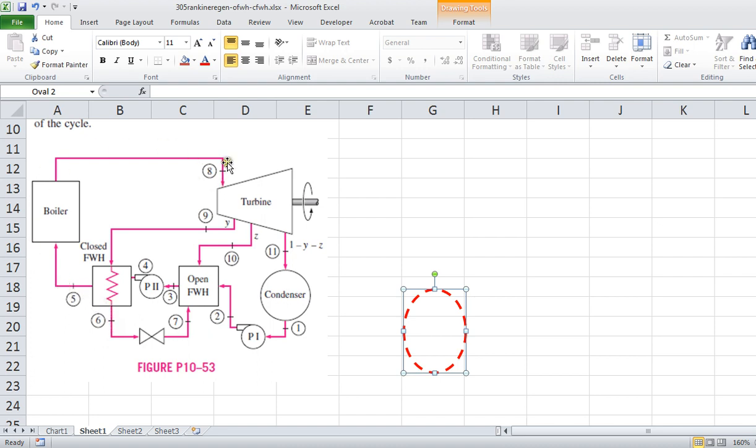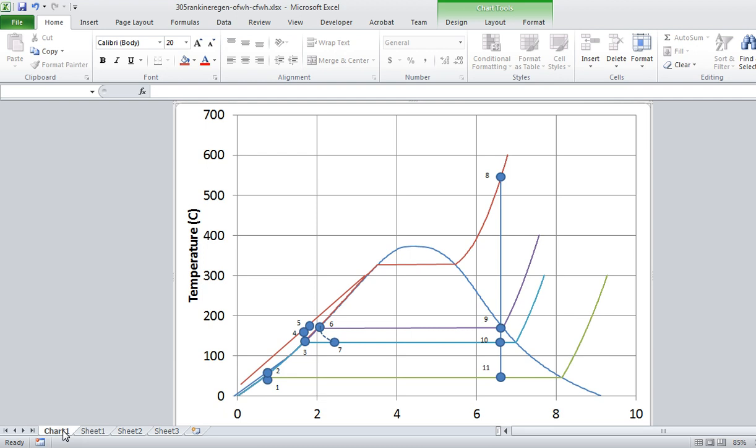Okay, so we've got all those points. We know the temperature going into the turbine, and furthermore, he did not say anything about this turbine's non-adiabatic conditions, so we have an isentropic expansion. That means entropy 8 equals entropy 9 equals entropy 10 equals entropy 11. So I've pretty much described this TS diagram that you see, and hopefully that all makes sense.